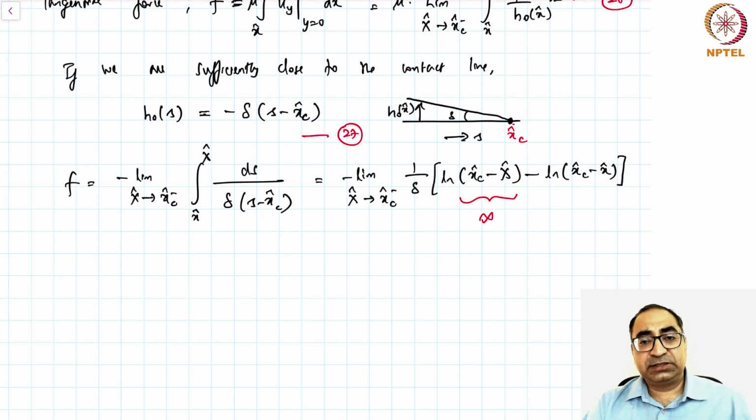So there are several of these suggestions, from kinetic theory, from non-equilibrium thermodynamics, plane slip models, diffuse interface models, precursor film models. There have been several of these models. One of the things that these models aim to do is to come up with a relationship between the speed of the contact line and the contact angle. Note that in our model, we have basically said that the contact angle, which we called theta at the beginning, was considered to be fixed. This contact angle does not depend on the speed of the contact line. But that is not the case. Experiments do observe that the contact line does move. It has a finite speed and the angle does change.